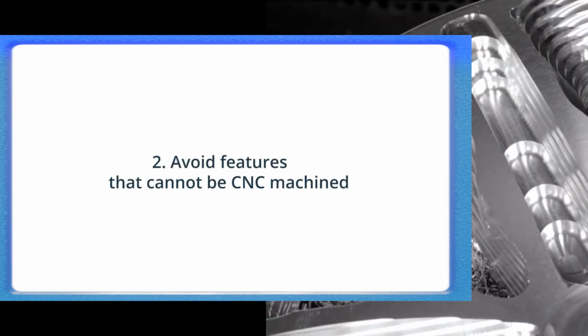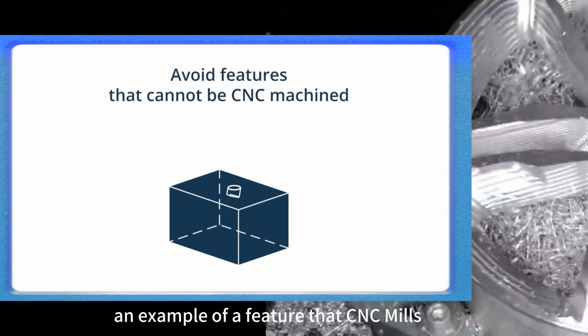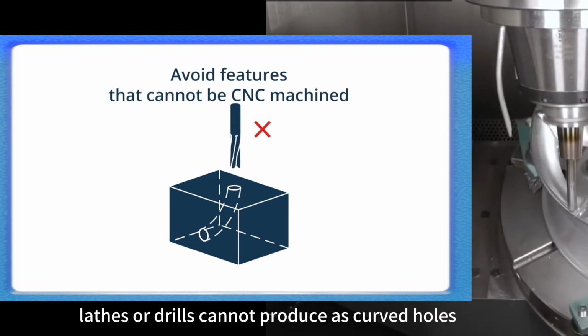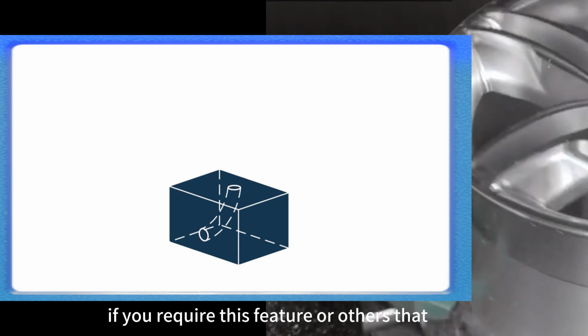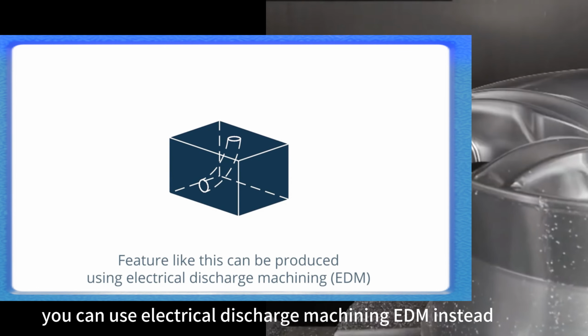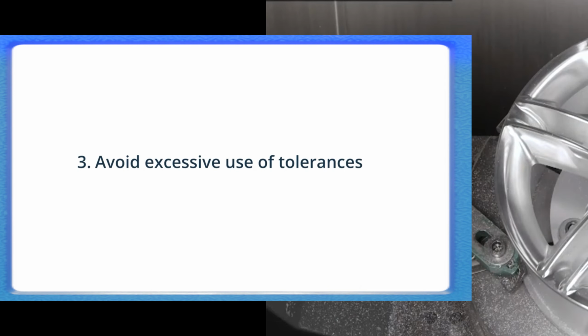2. Avoid features that cannot be CNC machined. An example of a feature that CNC mills, lathes, or drills cannot produce is curved holes. If you require this feature or others that can't be machined for your design, you can use electrical discharge machining (EDM) instead.